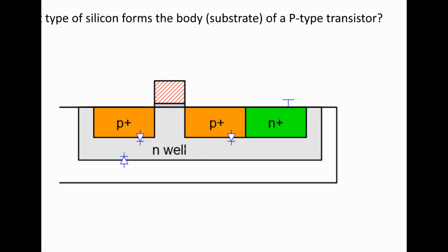the fact that that is the higher voltage and the P is lower would mean that the diode formed between the diffusion area and the well would be reverse biased, so that would disconnect the well from the source and drain. However, as we found out, it does still create a capacitor, unfortunately, but it doesn't create a connection. The N well is sitting in the substrate, which is p-type, which is going to be grounded, and so that also ensures that the well to substrate is also reverse biased.